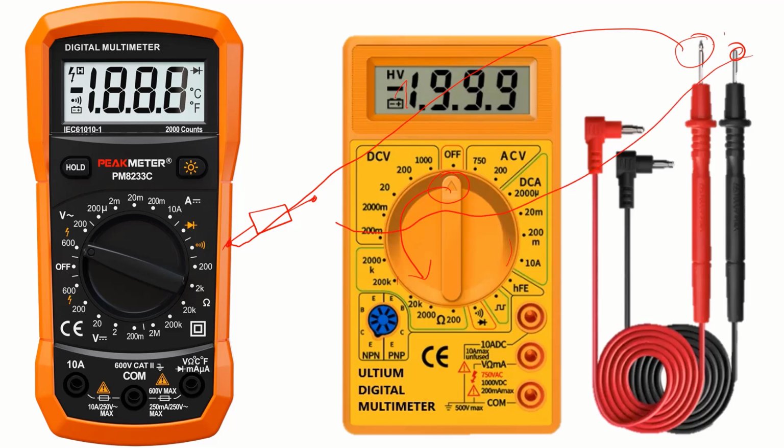Now you switch. It's always advisable to start from the smallest and you start going up. Always start from the smallest. So we can start from the 200 ohm. If you have no reading, it means the resistance of that resistor is greater than 200 ohm. So you swap to 2000. If you still have no answer, it means the resistance of that resistor is greater than 2000. You swap to 20k. That's 20,000. If you still have 1 shown here, it means that it's not in that range. So that's typically how it functions for all the respective regions.